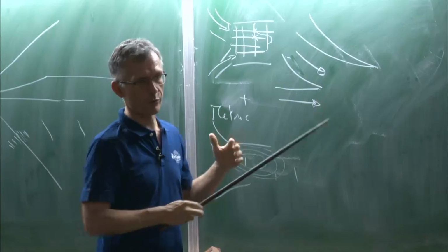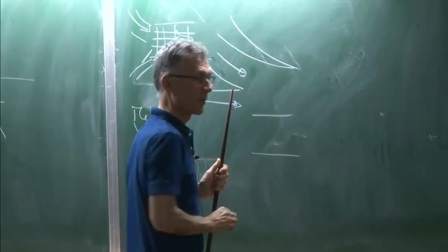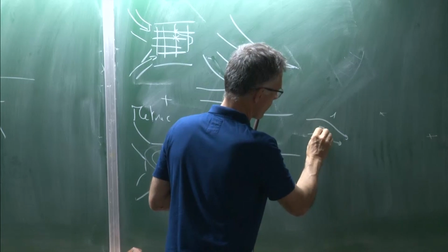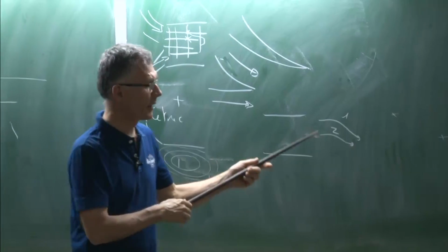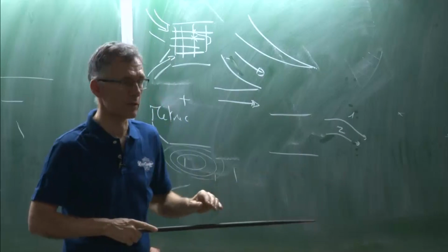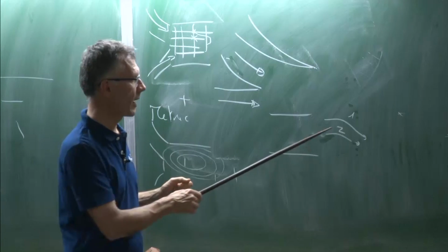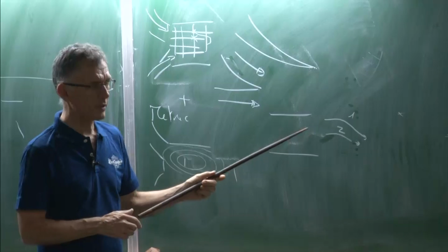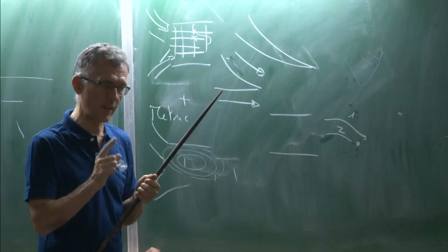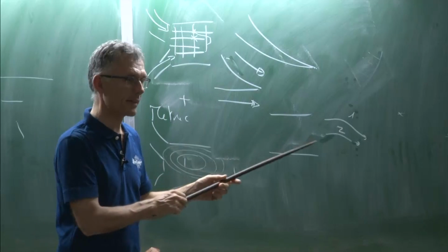The flow split depends on the pressure losses. Okay, you can imagine a swirler is actually a system where the flow is arriving like this, and here it can follow one path or another one. And it will split according to the pressure losses. If you block this one, everyone will go to 1. If you block the other one, everyone will go to 2. So the pressure losses in 1 and 2 should somehow be coherent if you want the right flow split. Even if you make mistakes on the pressure losses, you should make the same mistake on both sides. That was the key problem there. And so that the split remains the same.